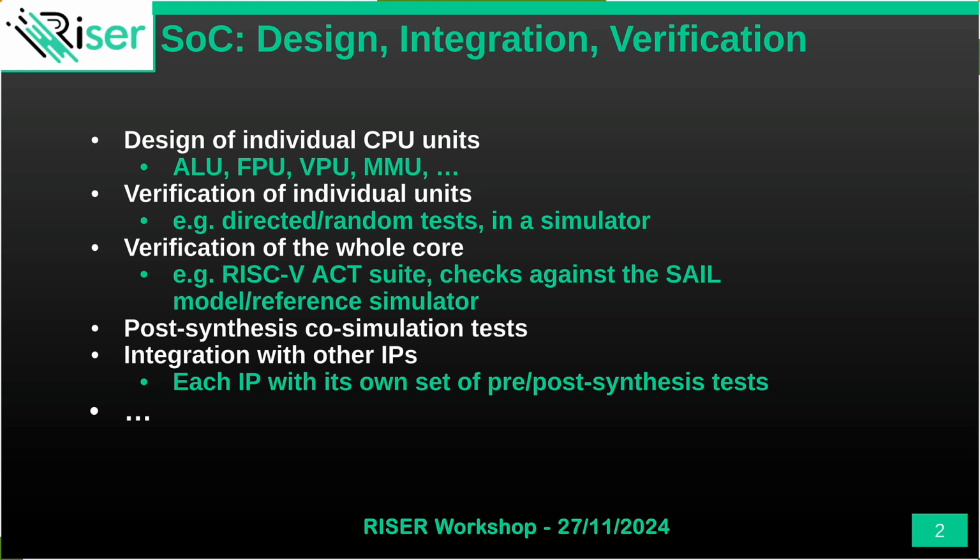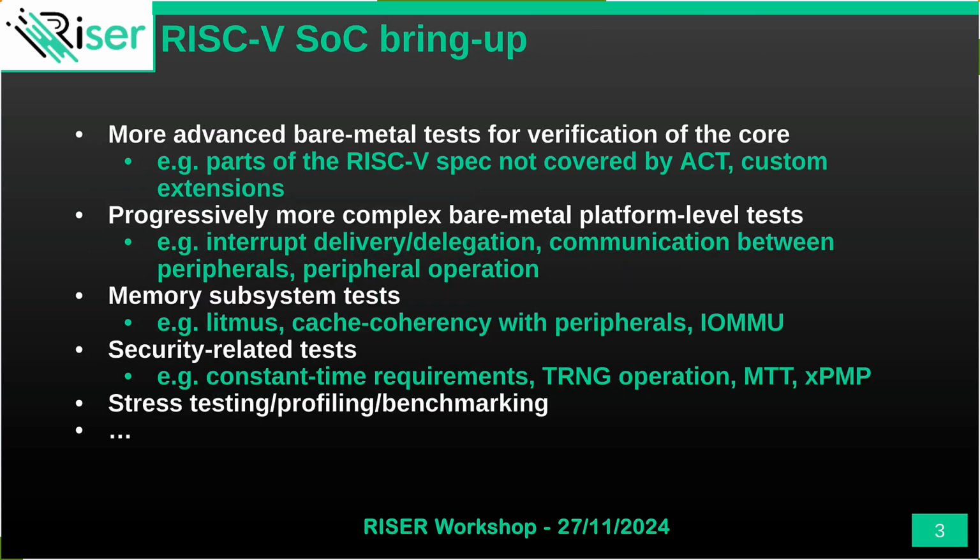They are there for basic stuff, especially those that run under a simulator before you do the synthesis, so you cannot expand the test coverage. You can only test for specific things and do very basic stuff there, or else it takes a lot of time for the test to work. And you want those tests to be part of your CI flow, so when you compile the hardware, before you create the bitstreams, those simple tests can catch bugs early on.